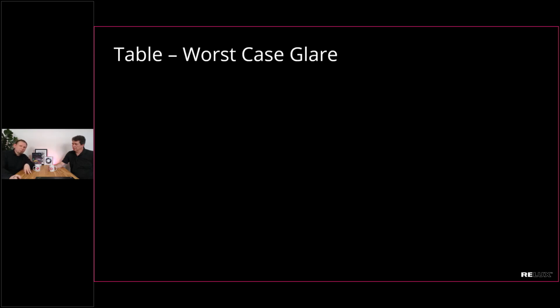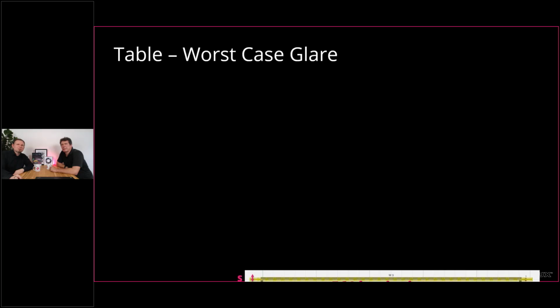So this should help you with a table to identify luminaires and their application in terms of glare, without having this expensive calculation of the UGR value. Because if you remember 1995, it was hard to find computer applications which could calculate this. So the idea was, okay, let's define a table, and with the table, you as a lighting designer can identify everything in your situation and have the UGR value ready. Table methods were in general quite popular in the 80s and 90s, and nowadays we have more and more calculation applications which can also do it on the side.